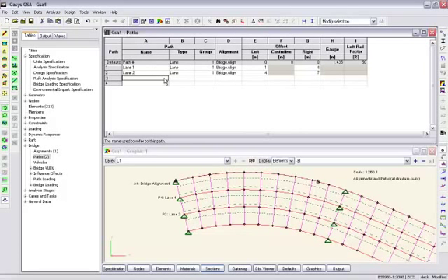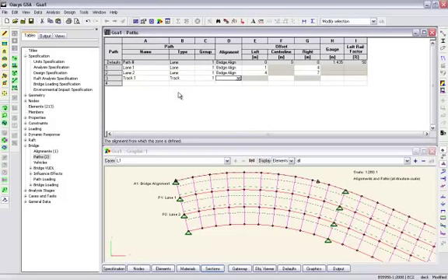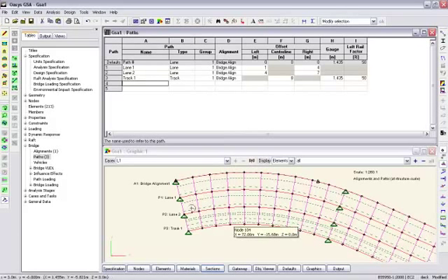And then finally I'm going to create a train track, which is a track type. You see this is slightly different. This gives the centre line this time over at 8 meters, and I'll take the default properties. So we've got two lanes of traffic and a railway line on this bridge.